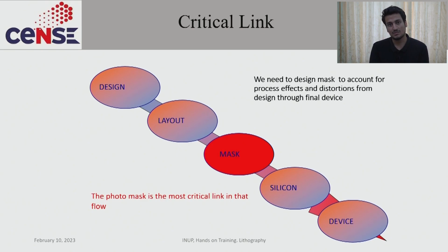So again, it depends upon the next process. Just suppose your next process is etching, so you want some specific area to be open. If your next process is lift off, so you have to make some other area as an open area. So again, it depends upon the post process. Depending upon that, and depending upon the type of resist which you will use, you have to make the design for your photo mask.